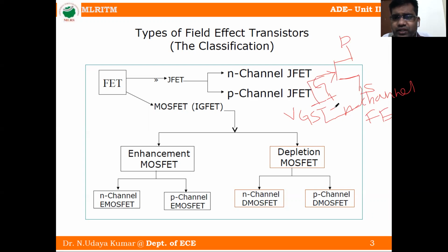And what about the drain terminal? The drain terminal is connected to the positive terminal of the battery. So this is the positive terminal, this is the negative terminal. Here is one ground. This voltage we call VDS, meaning drain-source voltage.